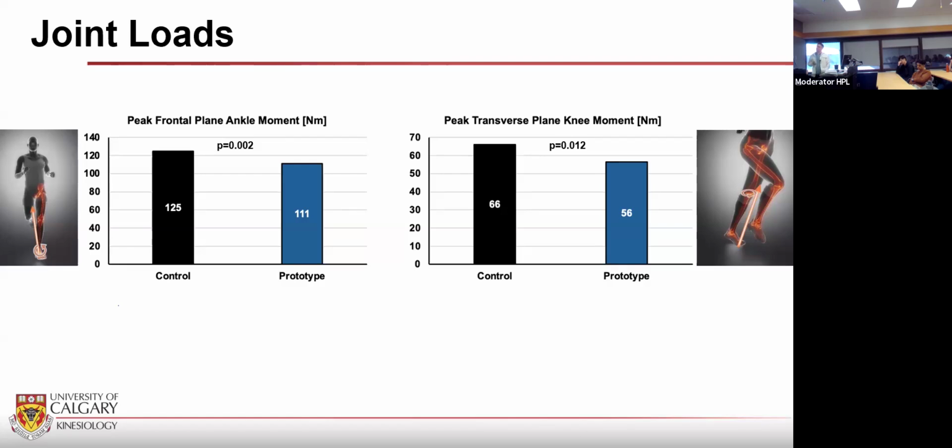So these results, while positive, were not as large as we were expecting. So we were expecting some much bigger differences. And so one explanation of that could be due to the fact that there may be some interaction between these different components. So having the optimal infill, as well as the optimal fiber orientation, they may have counteracted each other and not really attributed the way we thought they would.